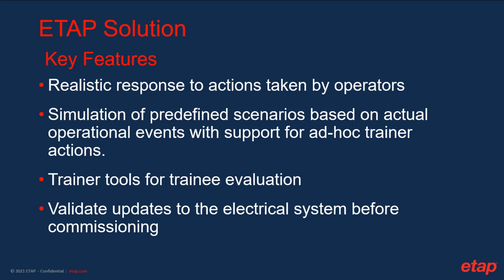We have simulation of predefined scenarios based on actual operational events that happened in the past, but also support ad hoc trainer actions. So ad hoc, a trainer can go and inject an event or a trip signal during an actual training session. Trainer tools are used for trainee evaluation, both in runtime as well as after the fact with reports and playback studies.